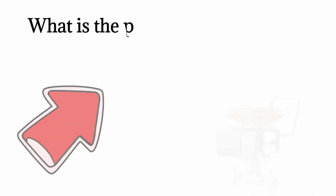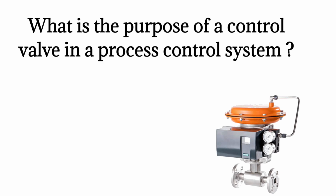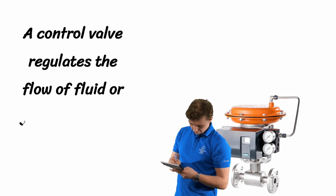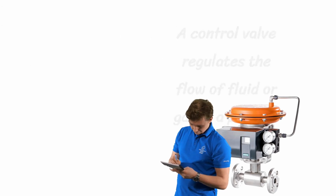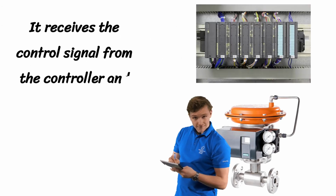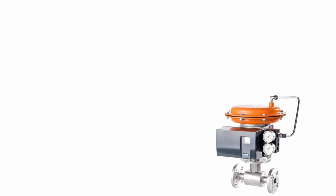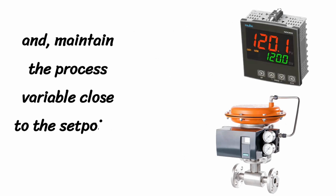Next question is, what is the purpose of a control valve in a process control system? A control valve regulates the flow of fluid or gas in a process system. It receives the control signal from the controller and adjusts the valve opening to control the flow rate and maintain the process variable close to the set point.